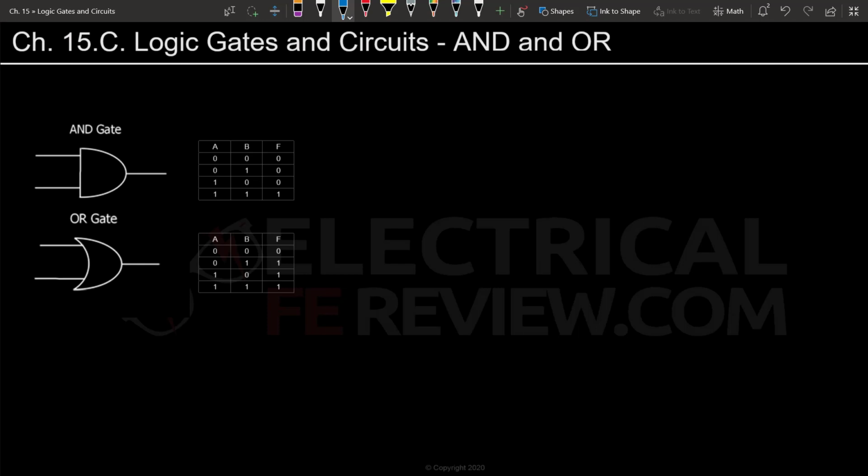For our OR gate, we can have as many inputs as we want. Of course, there are physical limitations when implementing these circuits, but theoretically we can put in as many inputs as we want. It will be on when either A or B is on, so also very intuitive. The only thing to remember is that for the OR gate, when both A and B are on, it also counts. So you're going to have a 1 just like the AND, but you will have these 2 additional ones. So that's a good overview.